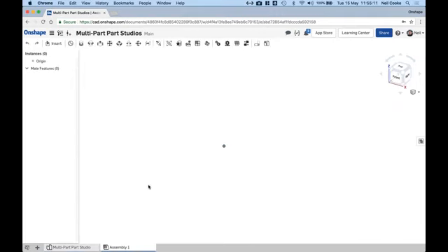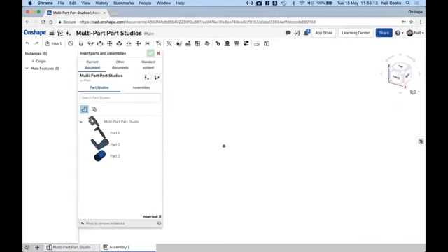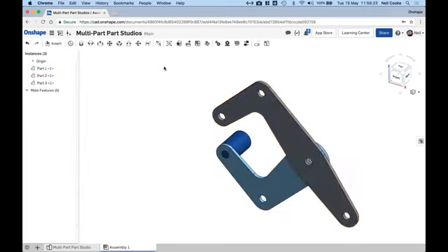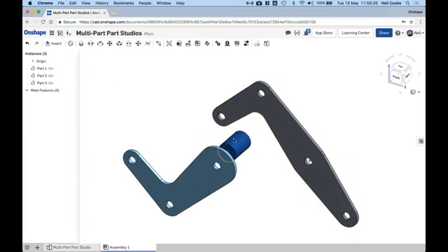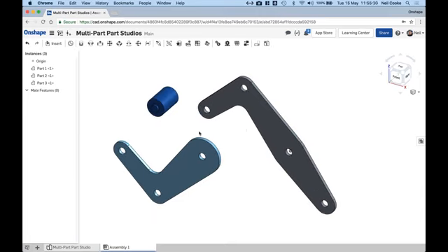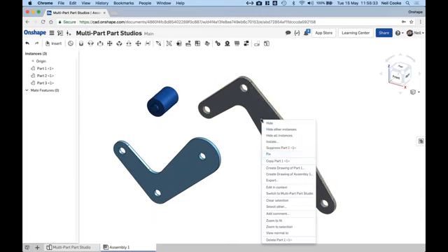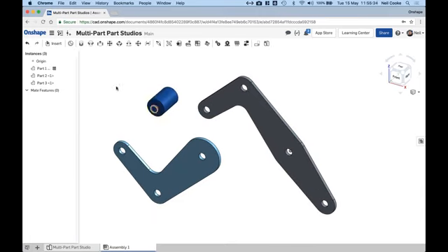And then when you create an assembly, again, these are slightly different. You can insert parts individually from a part studio, or you can insert everything. Now, as we saw before, these things are free to move. Okay, they can move wherever you want them to. So what you might want to do here is take one of these and fix it, and then just add some of these simple mates and say, okay, in this case, we want this thing to spin.